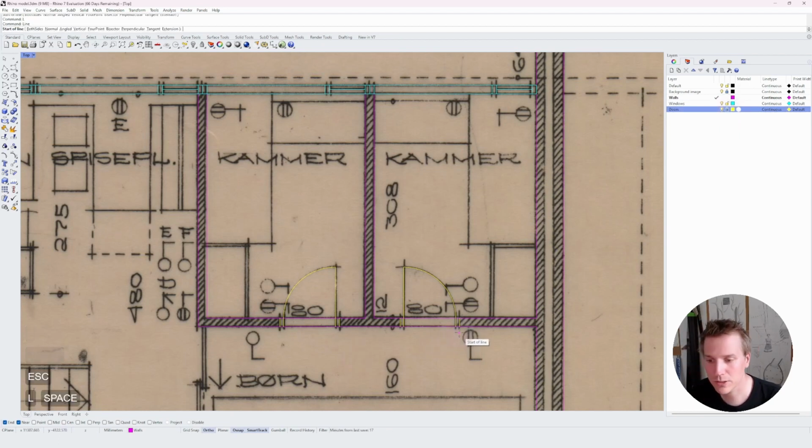And then I'll use the line tool to click here and draw where I want to cut. And because I have my doors locked, I can just select all of this, type T for trim, and then drag here and drag. Now, it doesn't look like I did anything, but I'll show you in just a second. For now, I'll just J for join, and I'll deselect.